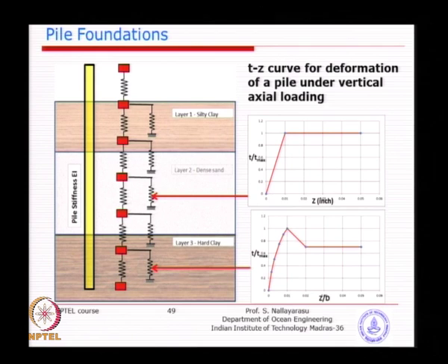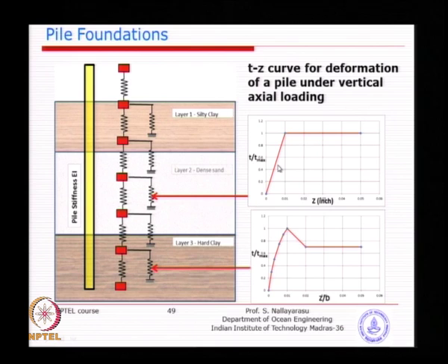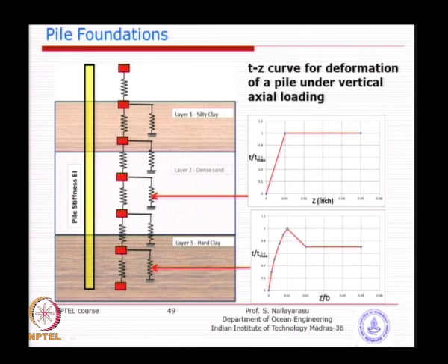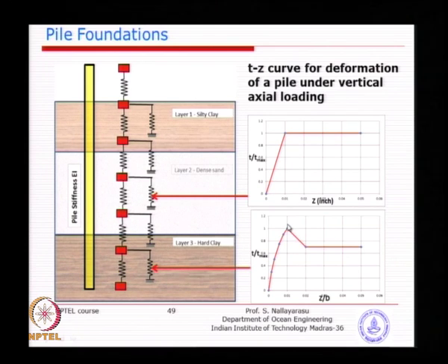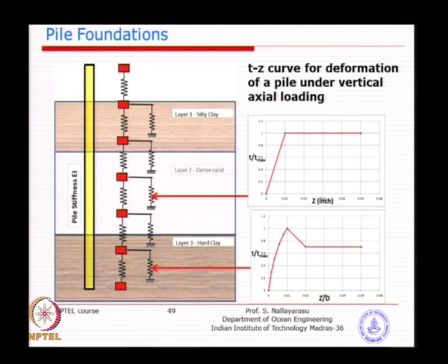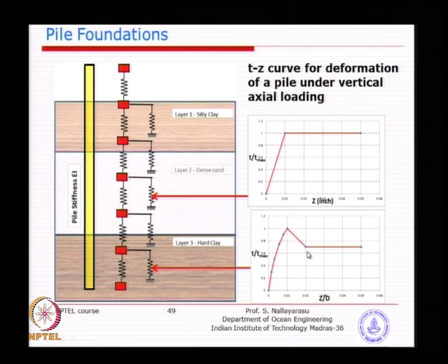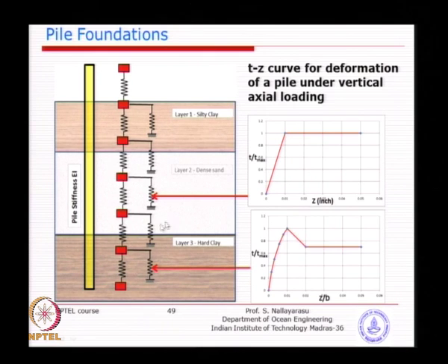If it is a linear spring like what you see in the first picture, for example, see here, it is a very good linear spring, goes to the maximum value and then it becomes plastic deformation. Whereas, if you see the second spring here, it is starting itself as non-linear, meaning the relationship is not proportional. It is going to be non-proportional in strength versus displacement, and then has a behavior which is getting degraded and then plastic deformation. So, you can see there are two different ideas proposed, tested and then validated.